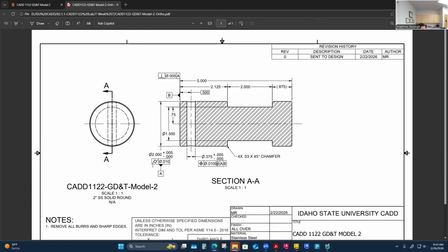What I sit here and think about is cylindricity, like axis driven. It is a diameter here, so I think I'm looking at a cylindricity of a diameter through here. If there was no diameter here, I think I'm expressing cylindricity of the outside surface through the part potentially. I'd have to look that up, but it makes me wonder. Definitely with the diameter sign and the tolerance on datum A, I'm looking at an axis type tolerance control. So okay. I'm just checking if there are some errors I've got to watch out for, but nothing stands out to me like it did on that last sheet.